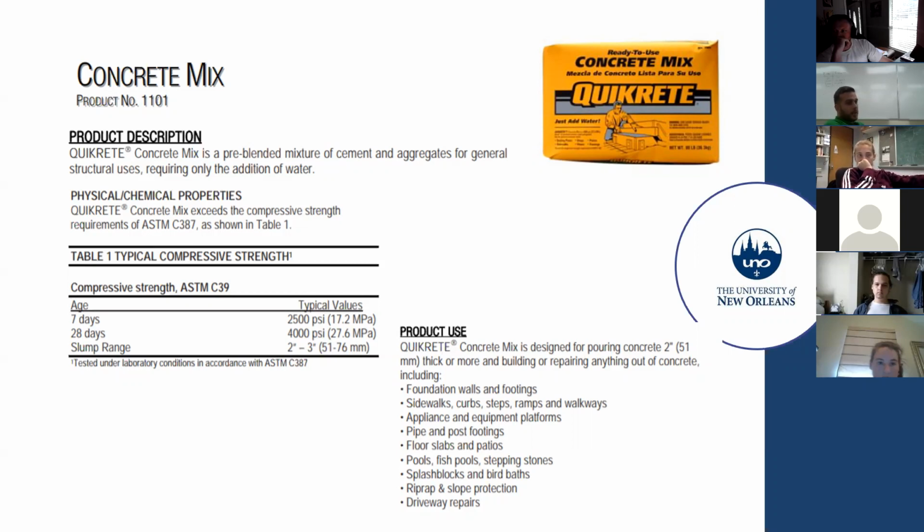Okay, so I'm going to tell you what I understand when I look at this table. So I'm buying this product, and I want to know what are the strength values that I'm going to get. What is the strength that I'm expected to have in 7 days? So I can open this driveway in 7 days or 28 days, let's say, without adding any admixtures. So I look at it and I see that on 7 days, I have 2,500 PSI strength. So I'm shooting for 2,500. If everything goes as planned, as expected, I'm going to get 2,500 PSI strength. If not, something is wrong.